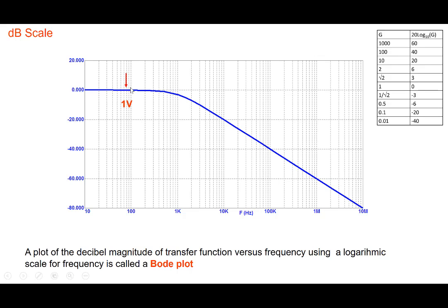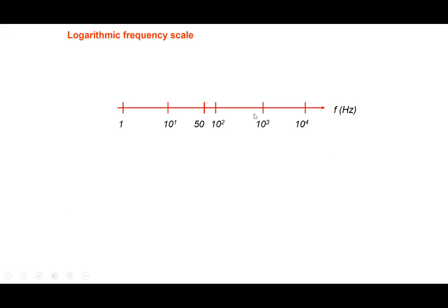Okay, so for example, if the signal is 1 volt here, that is of course 0 dB, and if we go here, we find this is 20 dBs below, minus 20 dBs. Minus 20 dB means 0.1, right? So the signal is 0.1 volt here. When we go here, it's 40 dBs below, so it's going to be 0.01, and so on and so forth. Here, 60 dBs below is going to be 0.001, 1 millivolt. All right, a few more simple things to keep in mind.